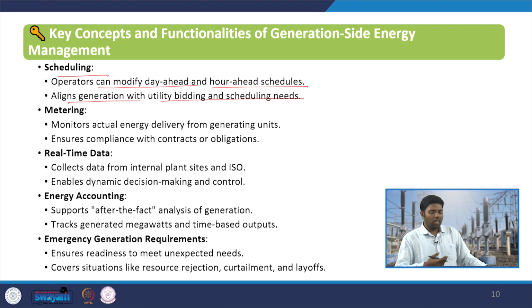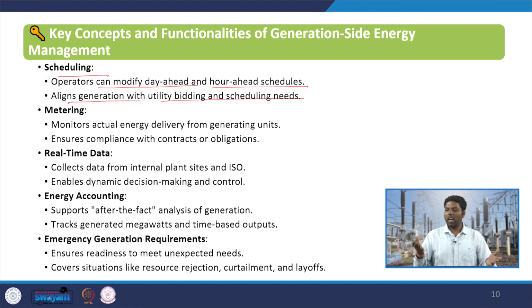That means, every time, even if you calculate day ahead schedules of your generators or your storage as a network operator, you again calculate even intraday, hour ahead or 15 minutes ahead, your real time situation. Depending upon that, to avoid any power imbalance or deviating from your economic scheduling, you see whether you are at the economic point or not, and whether the load prediction you have made is following your forecasted data or not, that is, whether the real time one is following your predicted data or not.